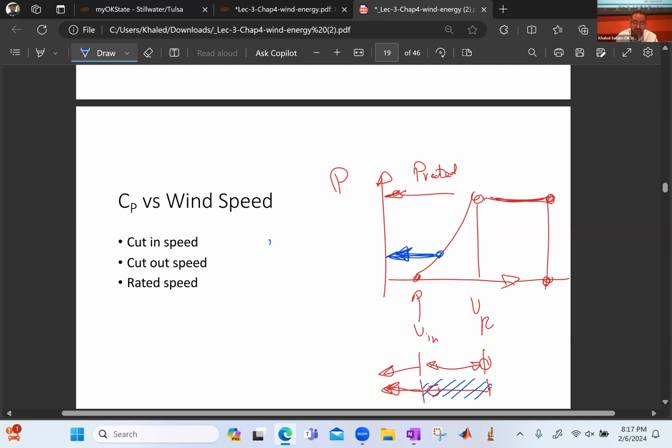Why? Because there's something called CF, right? With the CF, it means that you are not going to get 3 megawatt all year long because of the wind characteristics. So if the CF, let's call it 0.5, that means if you want 10 megawatt in that place, buy 20 megawatt worth of turbine. So this way, at the end of the year, they will produce as if there's 10 running all year long. That's the meaning of CF: the actual divided by the maximum possible.